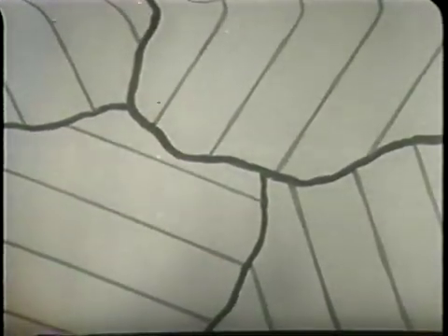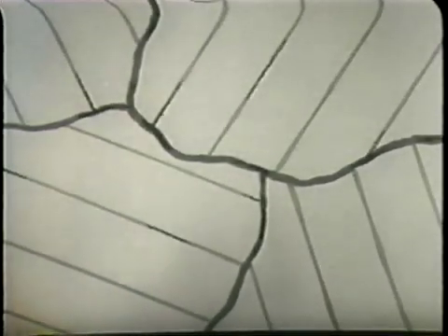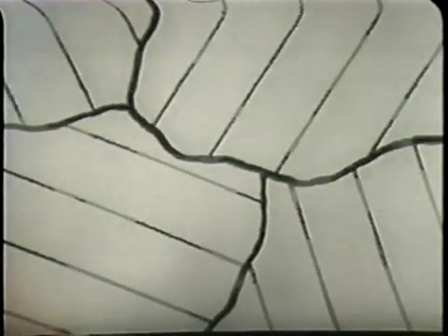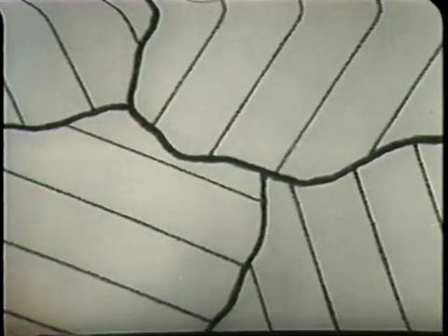Beyond this point, severe cold working may lead to more violent deformation, in which fragmentation and crushing of the grains occur. The total effect is to increase the metal's strength and hardness. One explanation of this effect is that disturbance along the slip planes and grain boundaries produces an amorphous material having no crystalline structure and therefore no planes of weakness. Thin layers of this material, stronger than the parent alloy, form along the slip planes and grain boundaries and serve as a cement to bolster resistance to further slip.